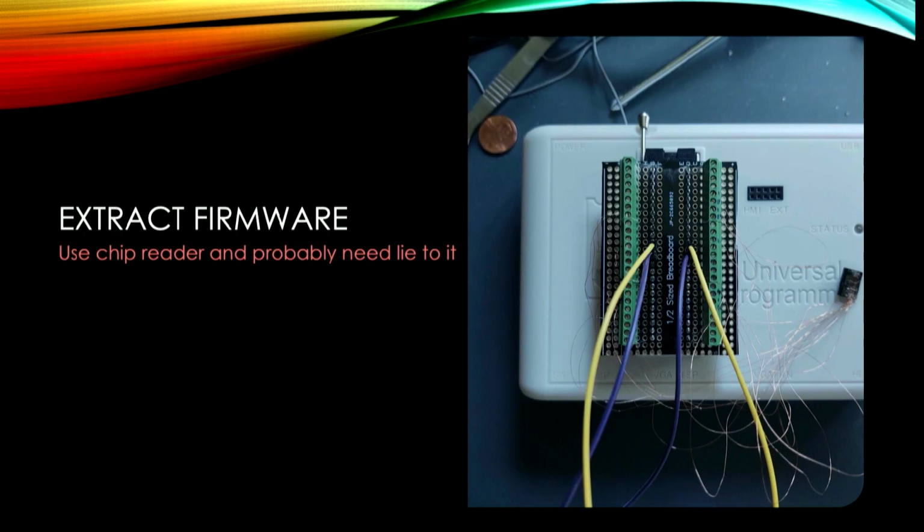But it's fairly easy. You have silk screens on these things that tell you things like, hey, it's 8-bit, so many bytes, a different structure size, and you get that information, and you just search through that manufacturer's list of chips. I typically like to look for ones that are TSOP 48 or 48-pin chips that would potentially have that same silicon underneath them. And then what I do is I wire this thing up like it's a TSOP 48. Plug it into my socket and pick one of their things.